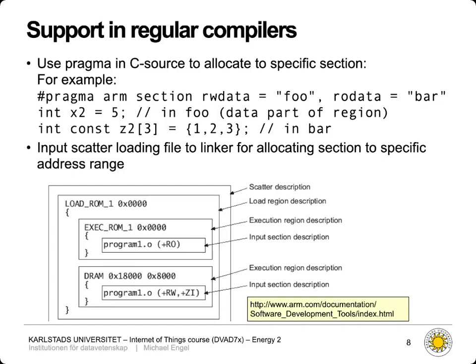So all the variables that you just declare but do not initialize directly with the declaration. And of course, you could add a second section for RAM, like an SRAM with our SPM memory, and you could put certain of these sections then into this specific memory. Now the problem is, well, this works already pretty well, but it's static. So if your program behavior changes, you might benefit from other variables being in your scratchpad memory. But since the linker script always fixes the addresses of variables in memory, you can't change this while your program is running. So you need a different approach to do this.